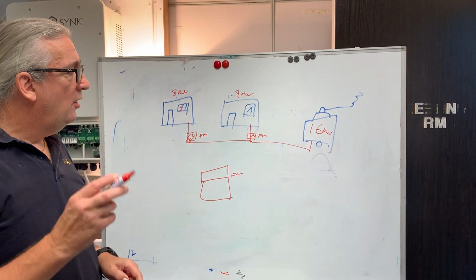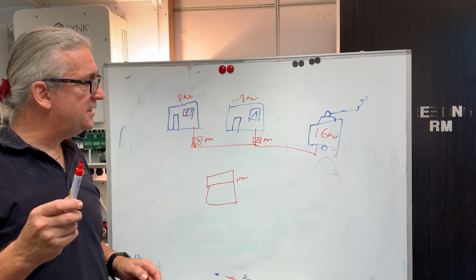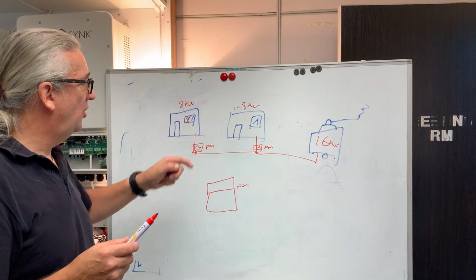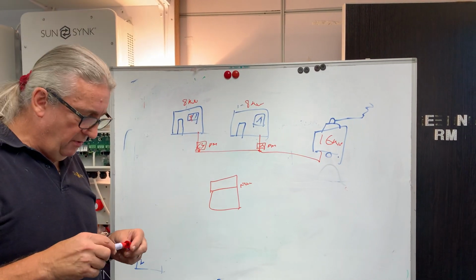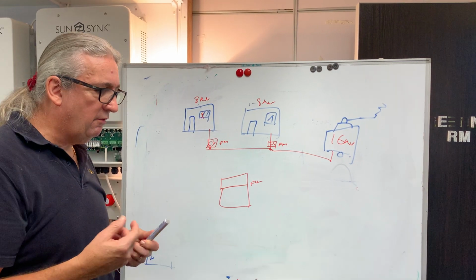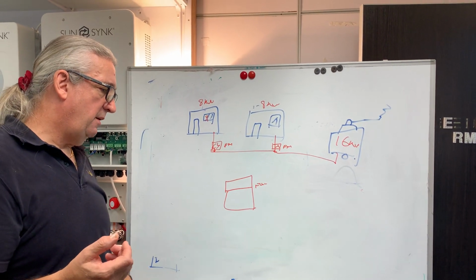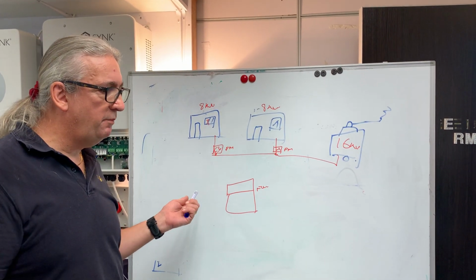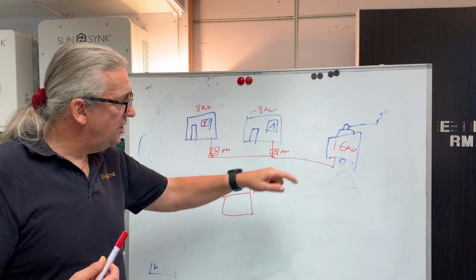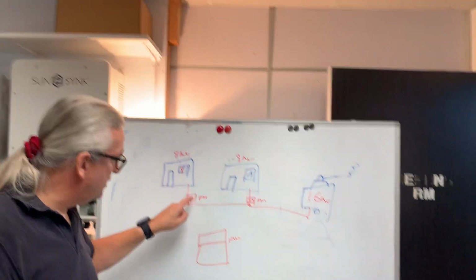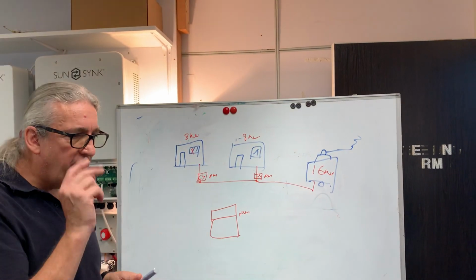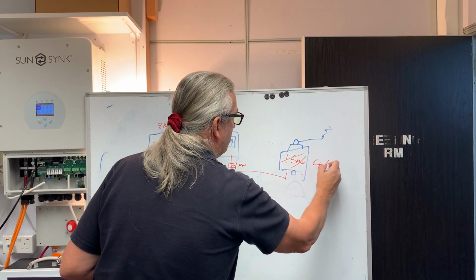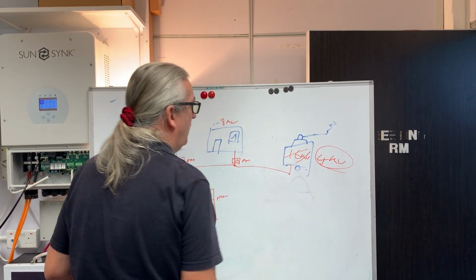This can give it. But the thing is, because you don't need it all of the time, you only need it on demand. You can't be switching a generator off and on, because you turn it off, he's got none. And because the generator motor is turning round, a typical generator may be using 100, 200 litres of fuel in a 24 hour period. By switching the generator off and filling the tanks, the power maker fills the tanks up, two things. One, we don't need a 16 kilowatt. Maybe we just use a 4 kilowatt generator, much smaller, less fuel.